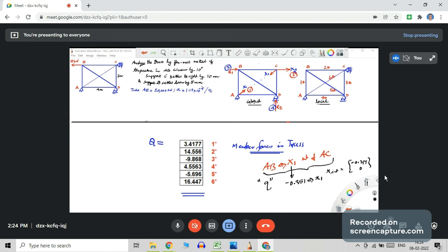If you are given a determinate structure, flexibility method can be used to find out the displacements, etc. There is no solution process. There is no inverting in that problem. Suppose you are given a determinate structure, when you write your solution on paper, you will not see any matrix inversion.